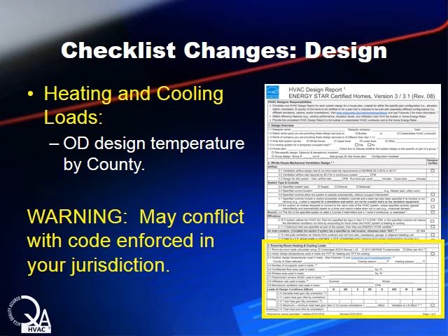I would check with your local official to see how they're going to interpret this requirement, and remind you that Energy Star concedes and acquiesces to the local code official. So as a designer, it may be that the code official allows it, it may be that they don't. I just want to offer you a warning to investigate that before you use a design temperature that may wind up causing some conflict.